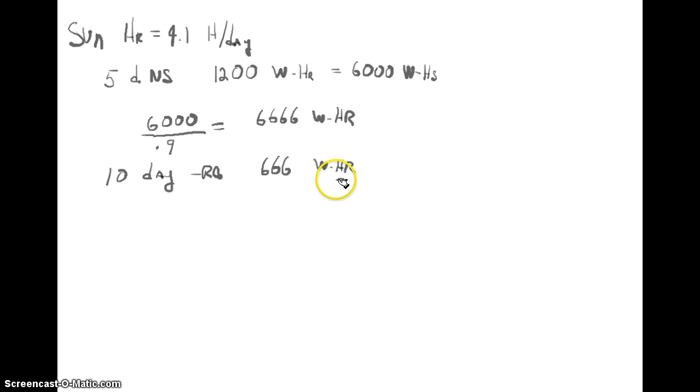Okay. So our total panel per day now has got to put back our daily average of 1,200 watt hours plus 666 watt hours. So our total panel has got to now collect 1,866 watt hours. We'll pick it back up on the next video.